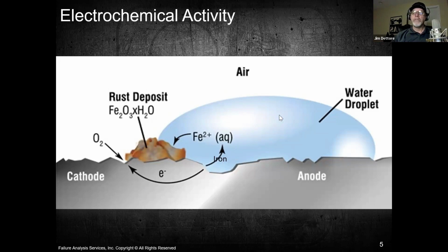Different electrolytes, what we wet that metal with, can cause corrosion rates to be variable. So some, such as the salt or potential gases in an exhaust gas stream in a natural gas engine, especially if we're combusting H2S in the combustion chamber, right? Very, very corrosive constituent.